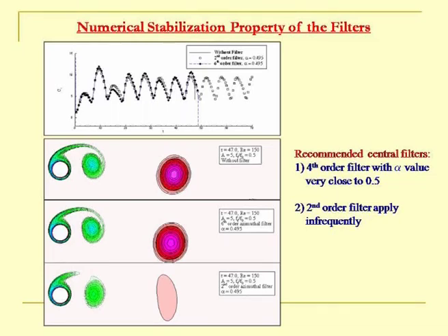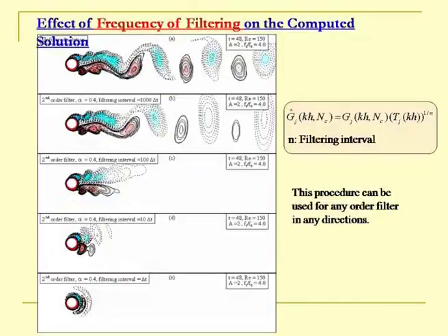So if I keep doing azimuthal filter, I may get around the instability problem, but then the vortical structures would take some unphysical attribute. Like here you can see this vortex has been detached already, and this vortex has also been stretched in the theta direction. So these are some of the issues that one needs to worry about.